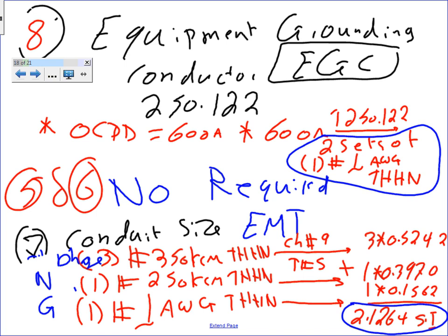I came up with 2 point. Oh, by the way, did we say what type of conduit we need? Did we emphasize? Yeah, it's an EMT. We're using EMT. Now, why should we pull an equivalent conductor with EMT? For reliability, better grounding, you can justify it to your boss. But do I need to pull an equivalent grounding conductor with EMT? No. But we're pulling it anyway.